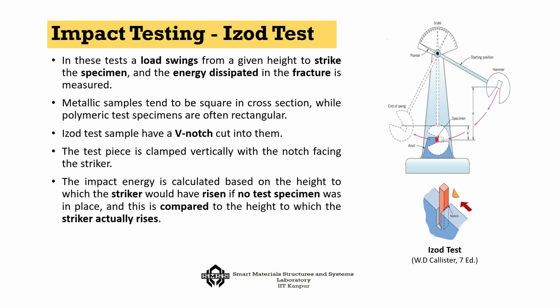This is important when you are absorbing some energy from impact, for example, how much of impact you can resist. Now, to do that you can do a test which is also popularly known as the Izod impact test. What you do here is that you create a material with a notch, and then you hit a hammer from the back side and you can actually vary this angle.